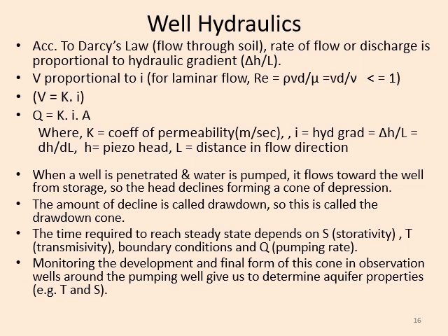So here, first we will know about Darcy's law. Darcy's law is applicable for the flow of any fluid, in this case groundwater, through a soil. According to Darcy's law, rate of flow or discharge is proportional to the hydraulic gradient.